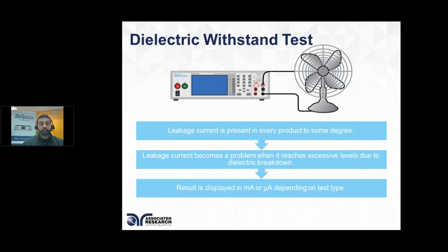Now, we have some medical device testing customers that run high pot tests at 4,000 volts. These are dual insulated products. They're making sure there's no connection to ground, and they're designed in a particular way that it handles 4,000 volts of high pot testing. That's not necessarily true for normal products. If you had a normal toaster or normal fan, the insulation is designed to withstand around 1200 volts of high pot testing.